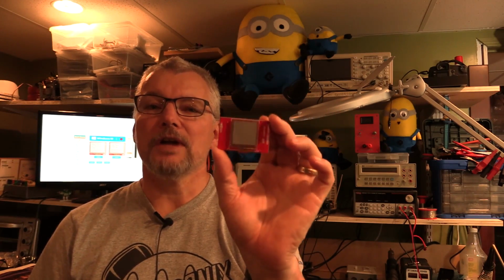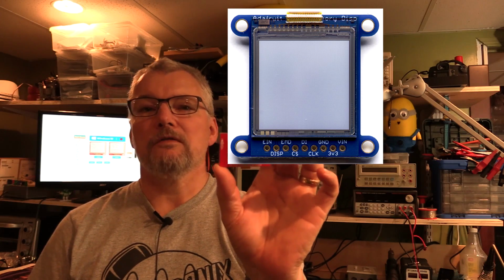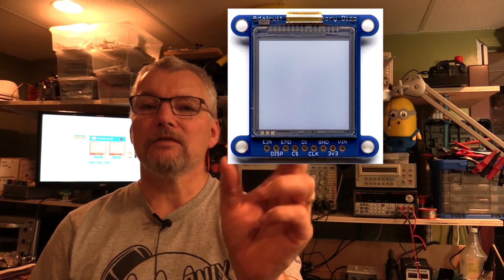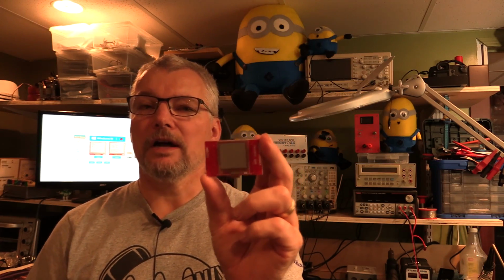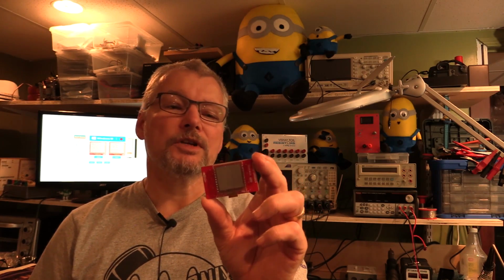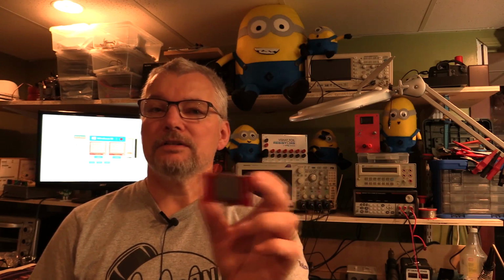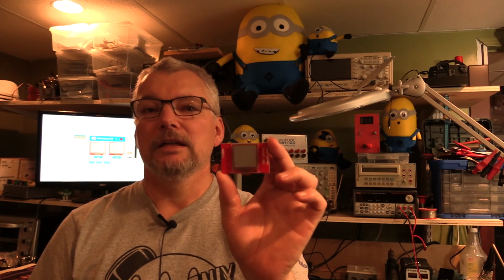Anyway, as I said, that's the display, and Adafruit has a similar breakout for this Sharp display. It's not in a booster pack format. It's just got the lines hanging off the side that you just plug into whatever microcontroller, whether it be an Arduino, a Raspberry Pi, or something else. And it will work just as easily with my software that I've written without any issues, because as I say, it's just SPI connected. So the hardware itself, this thing does not care. And there's a few things you have to pay attention to with these displays because of the nature of what they are.